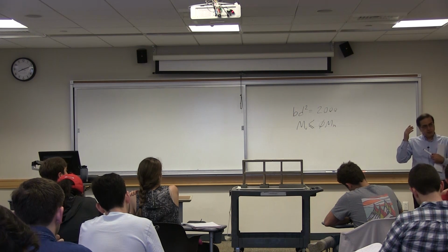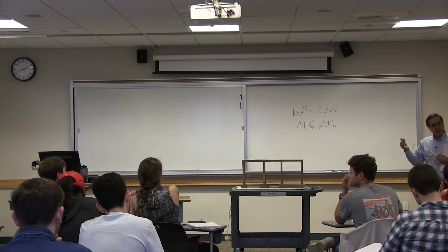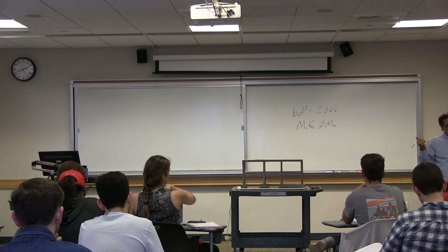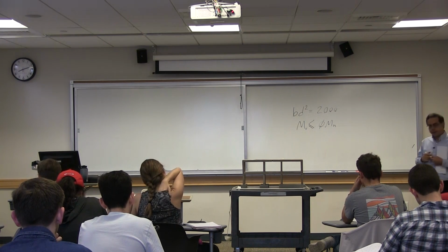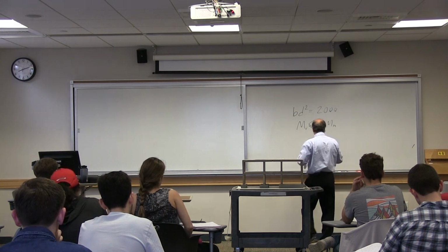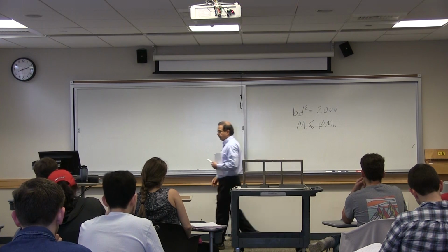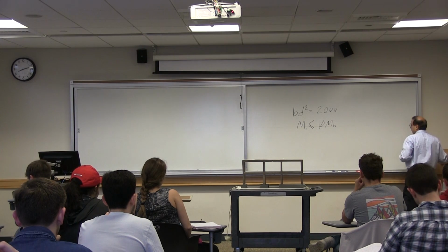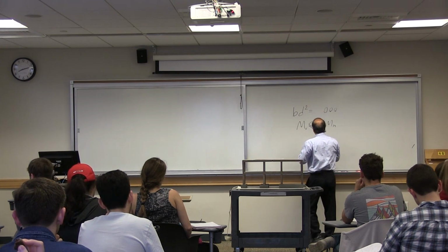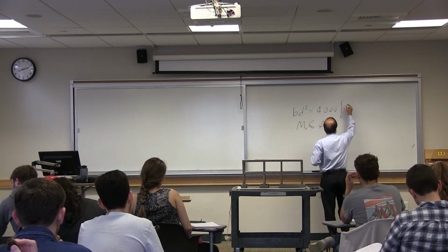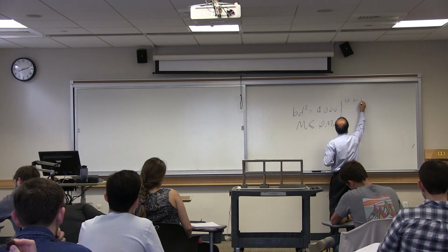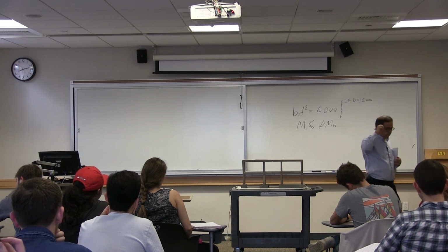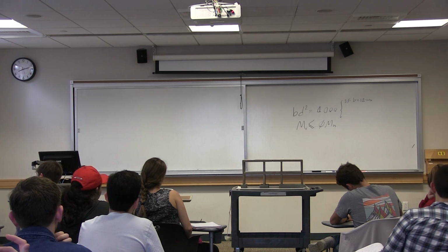One thing you might be thinking is that you round up your B and D. Is that what you are thinking? I'm talking about after we find BD squared. Let's just do this one. Let's say this is 4,000. We say, let's say B is 12. Can you calculate D? Divide 4,000 by 12 and then take the root of it.